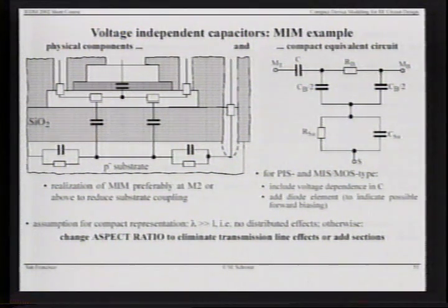This is the capacitance that we actually want. And all the other elements are parasitics that are unavoidable. For instance, there might be some contact resistances in the metal. There are certainly isolation capacitances. There's a usual substrate network. And we end up, again, with a compact model that is a three-terminal model where we have the desired capacitance here and a whole bunch of other elements that would degrade our quality factor but need to be included.